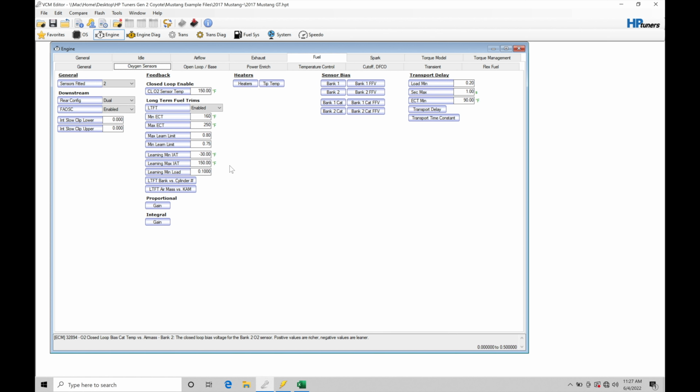By knowing this, the engine control module is able to look at the error and then start to ramp up the injector pulse width so we richen up the fuel delivery to the engine, or we increase the fuel delivery to the engine so that we're going to be putting more fuel into the engine, and then we'll have less oxygen content in our exhaust stream, which will bring down the reading and get us closer to the desired target. Likewise, if we're going to be delivering too much...